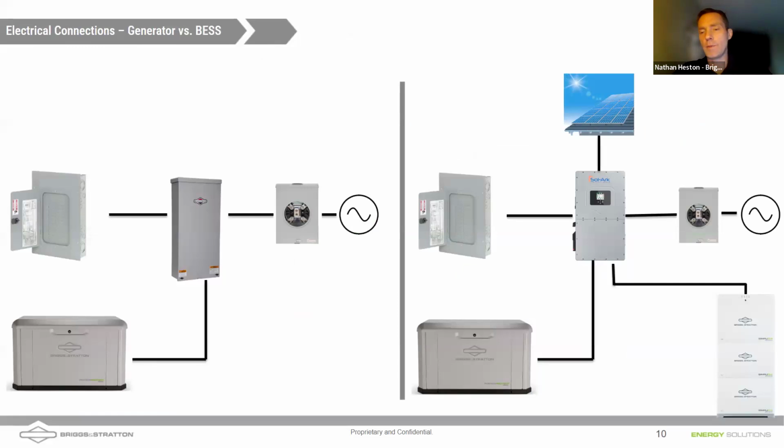So these interconnection transfer switches that are inside the Solarc are really relays, large relays. And it's got a separate generator port. Now, there might be a desire for a transfer switch still, and Daniel and I will talk about that later. So I was just helping an installer yesterday with an AC coupled system and a generator. What you can do is use a transfer switch to bring either utility or a generator, kind of like in the example on the left, into the inverter.